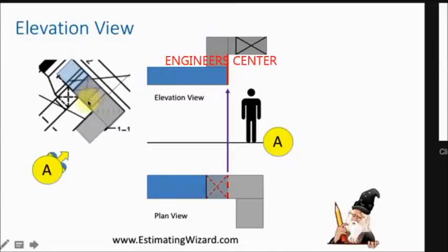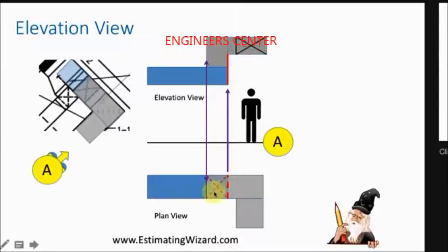That's back here. So that's how you determine a hidden line. And that line there is solid because you can see that line. So this right here is all solid because you can see it. If you were looking down from here, you could see it, like here. You can see it. So that's how you tell a hidden line.